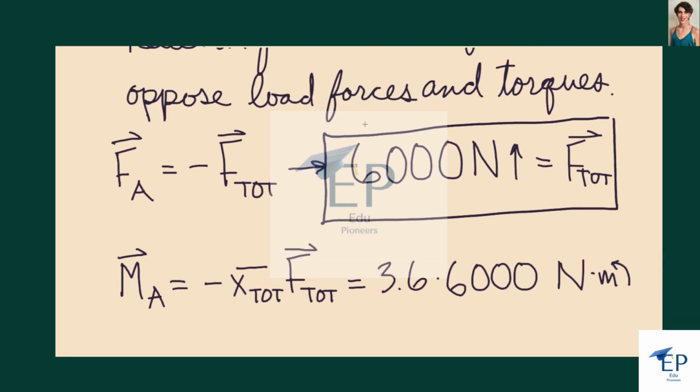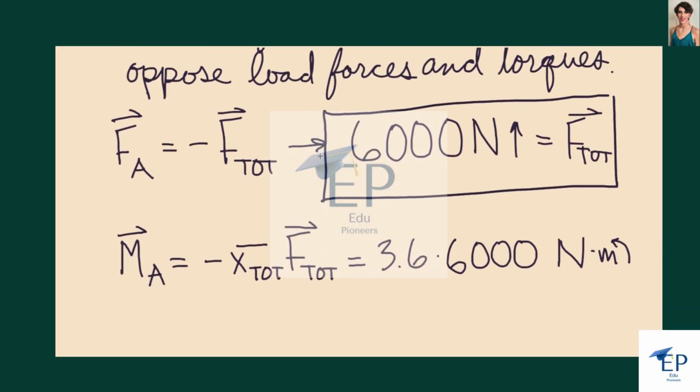Secondly, since our system is not rotating, and there is a total load about the support, there is some moment about the support. So there's a torque exerted on our support. Since we know that the torques must also cancel, there is an exerted torque at support A that must exactly oppose the torque occurring about the centroid.